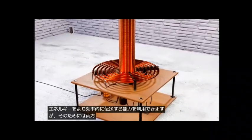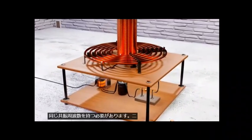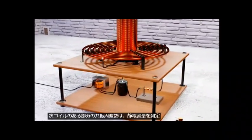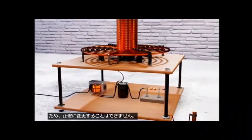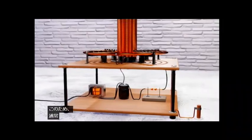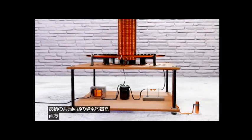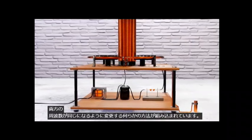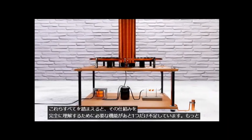But for this to happen, both circuits must have the same resonant frequency, and the resonant frequency of the section with the secondary coil cannot be precisely modified, because there is no capacitor to which we can measure its capacitance. For this reason, some method is usually included to vary the capacitance of the first resonant circuit, in such a way that both are the same frequency. With all this, we would only be missing one more feature to fully understand how it works.